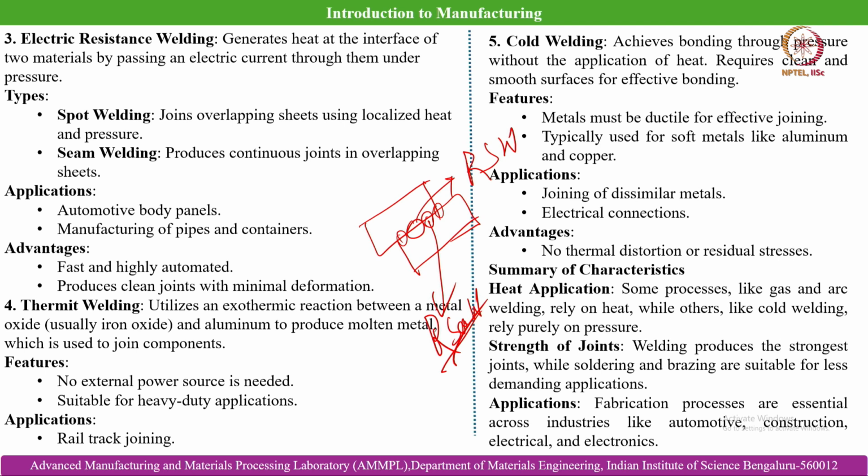And then here comes thermite welding. Thermite welding is very interesting. It can basically be classified as a mini casting process. Often we see the thermite welding process in the case of railway tracks, because this technique was invented much before the electric resistance welding processes, and railway tracks can be in locations where electricity may not be available nearby.